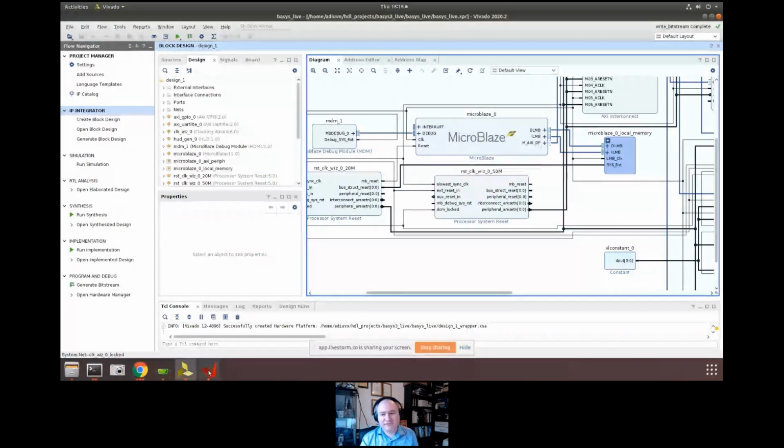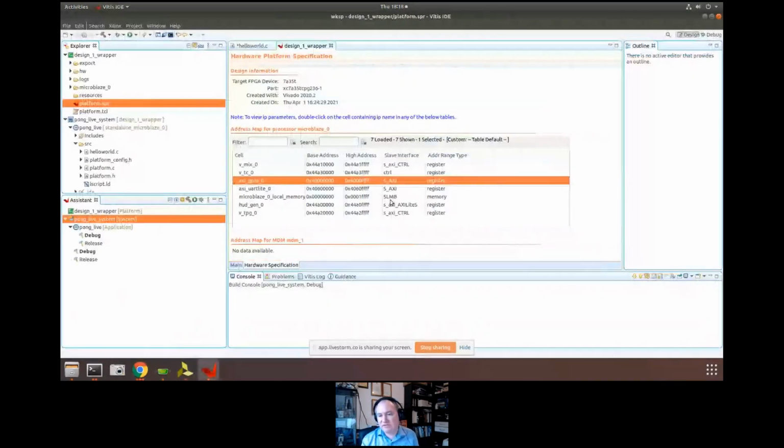And if you were to follow that through, and we can talk about that offline if you've got any questions, you'd see that this address here, this 0x4, is the starting point for the AXI peripherals addressed to that bus. And it's not an unusual memory address. Like I say, you'll see it on the Xilinx. It's quite common across the Xilinx MPSoC. Off the top of my head, I've not tried it on Versal yet, so I don't know if Versal has that same sort of approach for low speed interfaces or not.